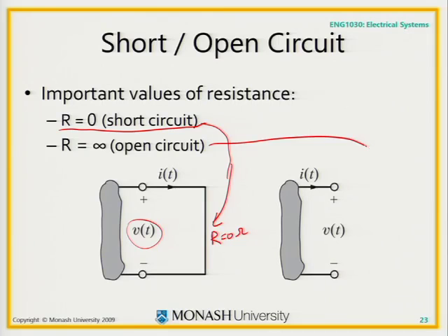If we have an open circuit, which is what this is called, the resistance across these two terminals, so if I connected an imaginary resistor, this resistor would be equal to infinity. You've got to turn your head sideways. It'd be equal to infinity if I have an open circuit with nothing connected across it.